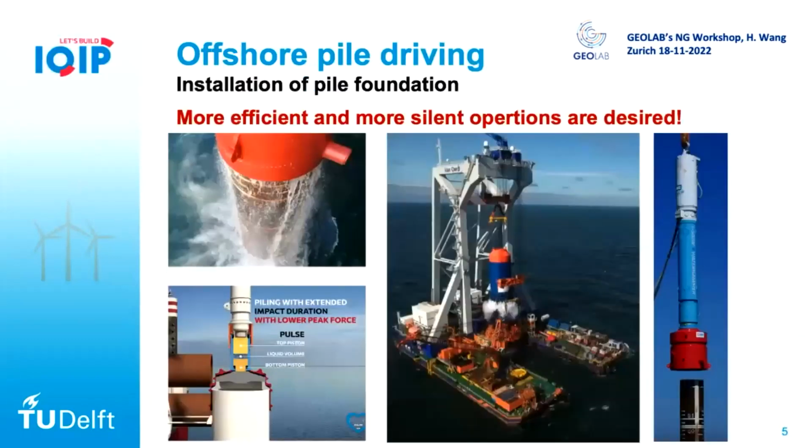So back to the monopile foundation, I think the first thing we need to consider is how you are going to install the monopile foundation. Because the monopile is quite different from older piles because it's very huge. The diameter can go to 10 meters nowadays, and people are talking about 15 meters. And the embedded length is quite shallow, less than 5 times the pile diameter.